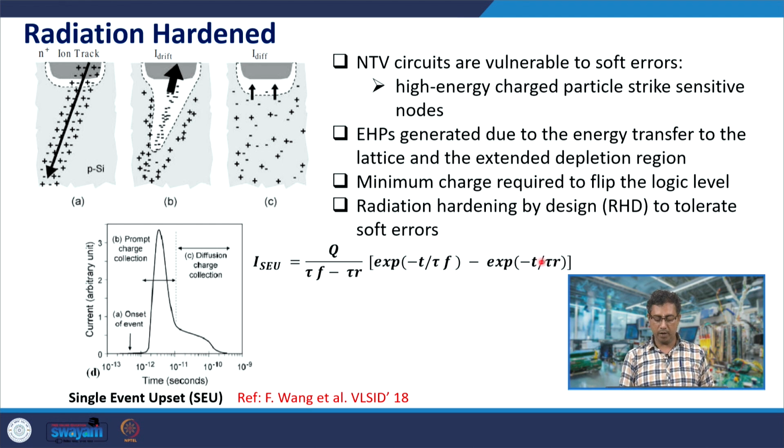So, this is a small initial transient which can be seen, and this would evolve in the long term. Initially this is like value 1 because tau f is very large. So, initially this is like 1 minus e to the power minus t by tau r. So, it rises, and after that this starts dominating and this dies down. So, you find a fall because of this. From this point it is this which dominates, and initially it is this 1 minus e to the power minus t by tau r which dominates.